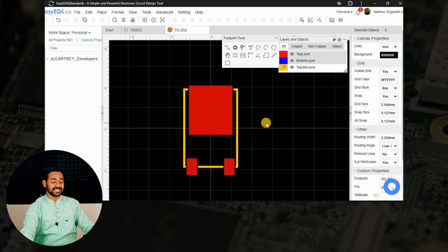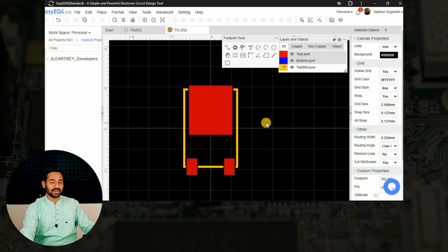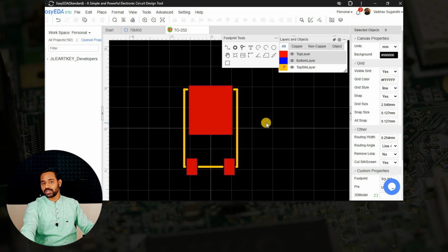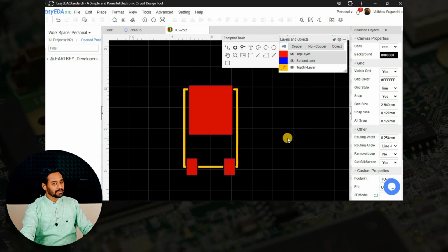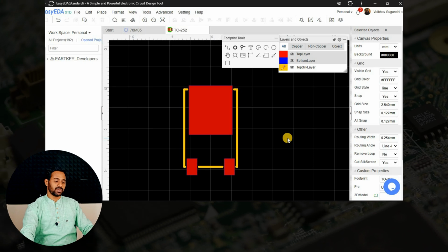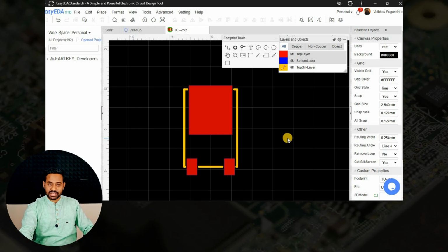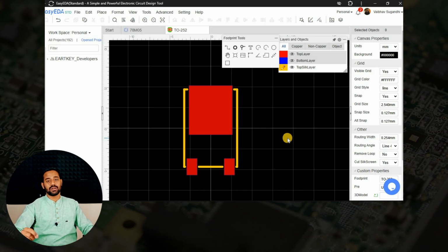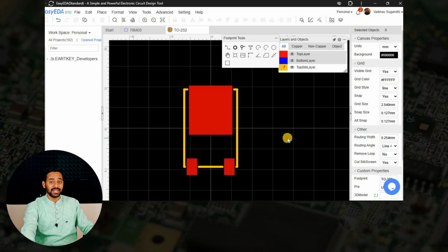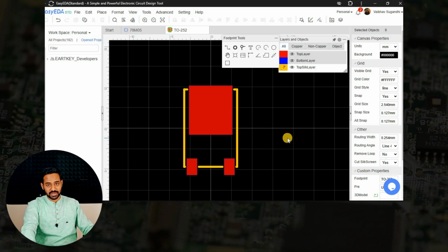Alright, now you can see that we have completed creating a PCB footprint with a DPAK, or maybe TO252, package as mentioned in the datasheet. Dimensions are pretty complex with respect to a DPAK IC. It is okay to do a little bit of verification against the datasheet information and a regular IC, or a physical IC if you have one in your store. Just make sure that all the dimensions match properly.